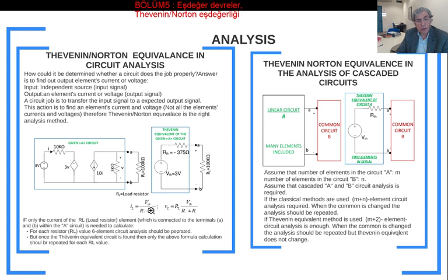The advantage of this formula is this. You could use this formula for any load that you connect to this. That means instead of 100K, you can use 25 ohm, or you can use a 1 kilo ohm resistor, and you're going to use these formulas only. That means you are not going to find the Thevenin equivalent each time. You found the Thevenin equivalent once, and for each load, you're using the same formula.